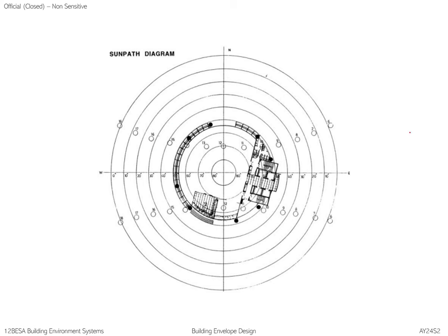So, sun path diagram. This is from the 80s, 90s, right? We don't have the benefit of the technologies we have nowadays, so this is the typical way that we did the sun path. You can see from east to west, east, west, north, south. The degree from the horizontal, and then at that time of the year, the specific month, the specific hour of the day, where the sun will be.